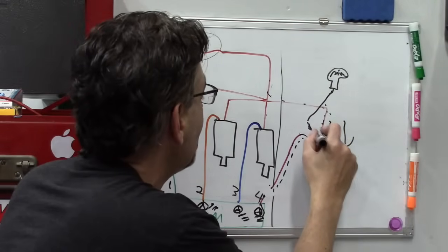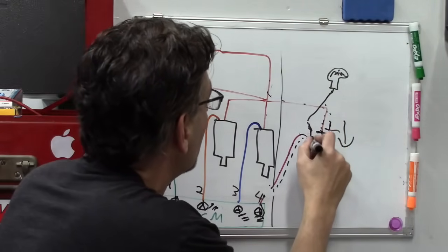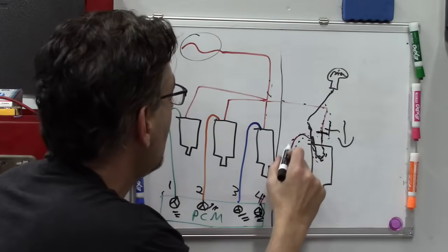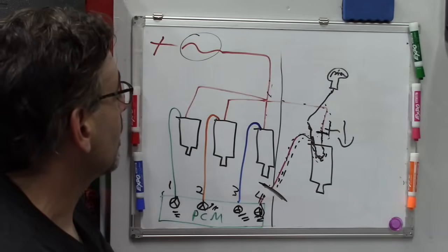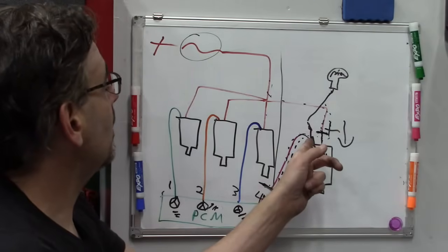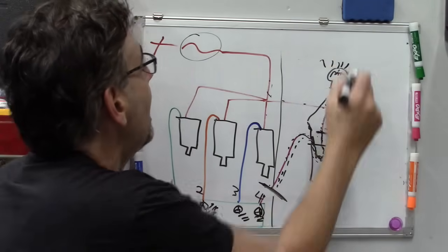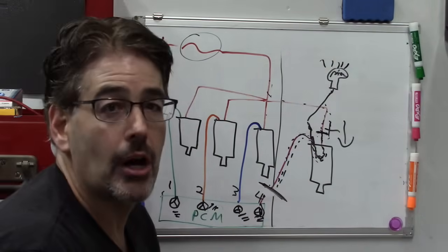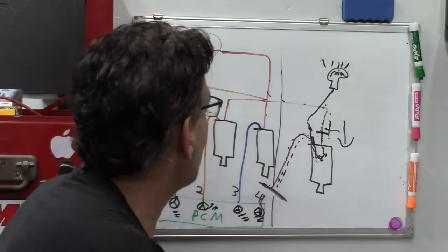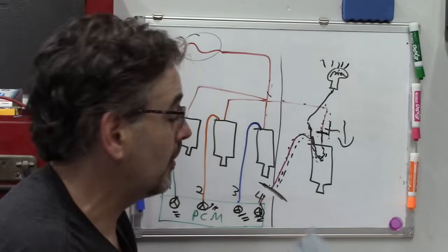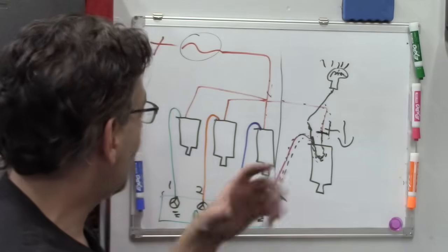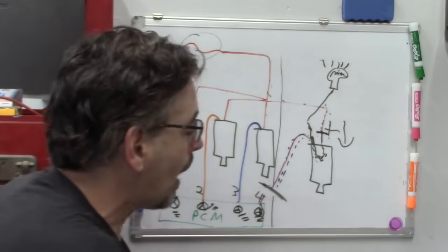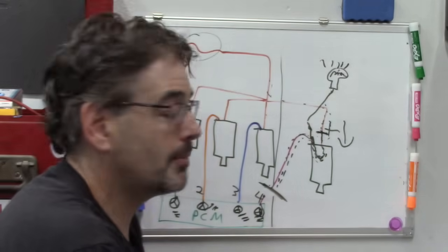Connect it back up again, now our power goes through the injector, but it still ends here, but it's still present here, so my light lights. And that's how I was able to know that I was on a ground. Again, if you're still not following that, review that basic electrical series and it'll make sense. But I'm able to do that right in the field. I can take one look at that wiring and I go, oh, I know how I'm going to test that.